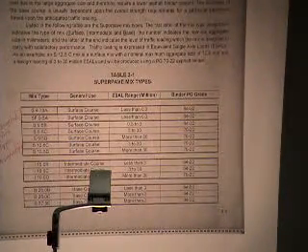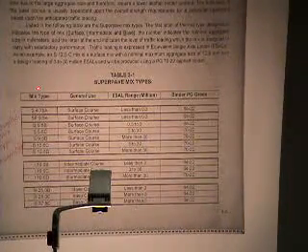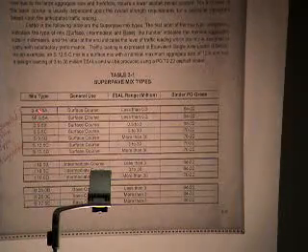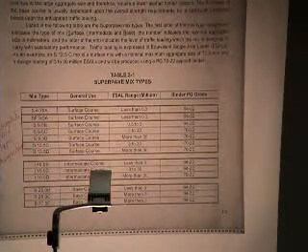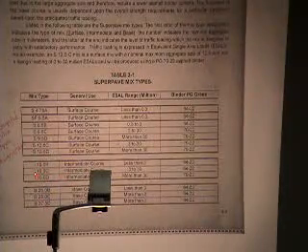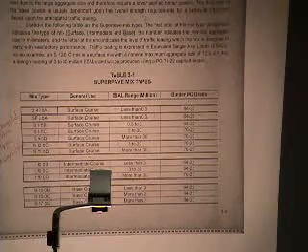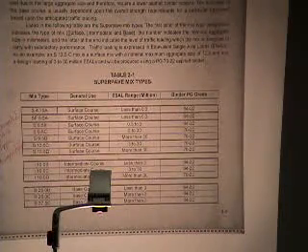But in any event, it's related to the top size aggregate in that mix. If you'll notice here, we've got 4.75, 9.5, and 12.5 on surface mixes, 19 on intermediate, and 25 and 37.5 on a base mix. Now those numbers are in millimeters.